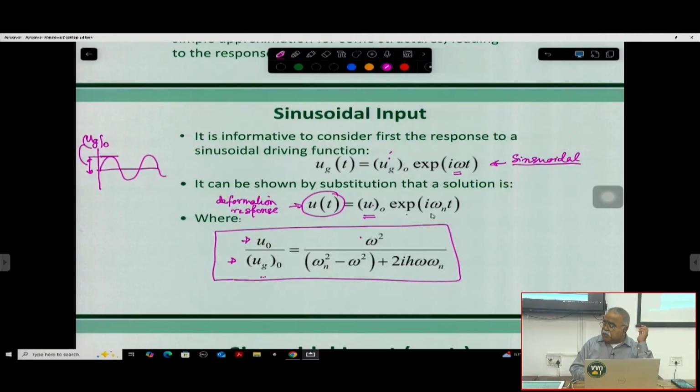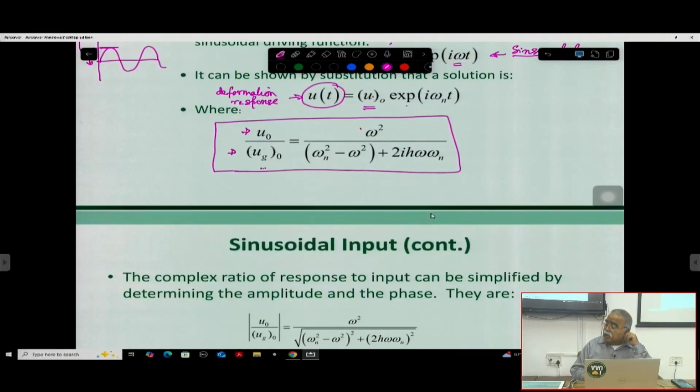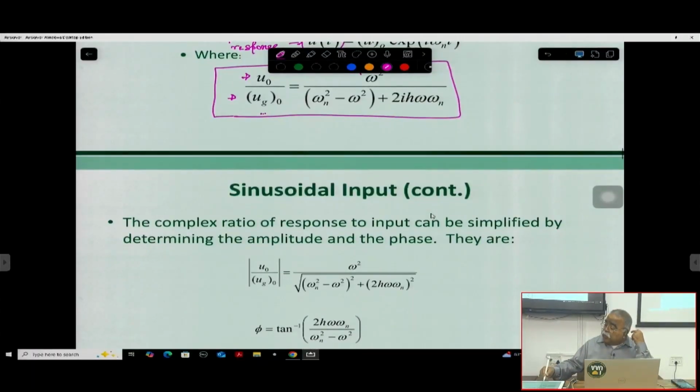Right? And this equation you have already learned in your vibration chapters in physics and also in many contexts. So I understand that this thing is known to you. So the maximum amplitude of the building, for a given maximum amplitude of the ground, you can calculate, provided you know the frequency of the earthquake and also the natural frequency of the building.